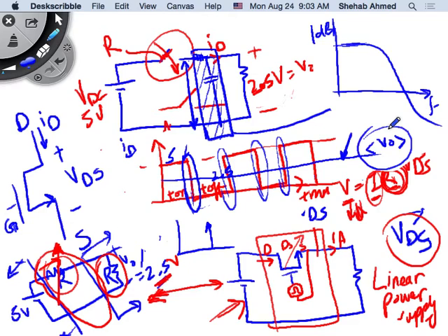If you have a signal x of t, the average value is one over the period times the integration of the signal over the period. The ANs and the BNs were multiplied by sine and cosine functions. These were all the AC components in the signal. Any signal that is not a pure, smooth DC will have a DC component and an AC component. The AC components are all these ANs and BNs or CNs multiplied by sines and cosines in the Fourier series, and the DC component is the average value.